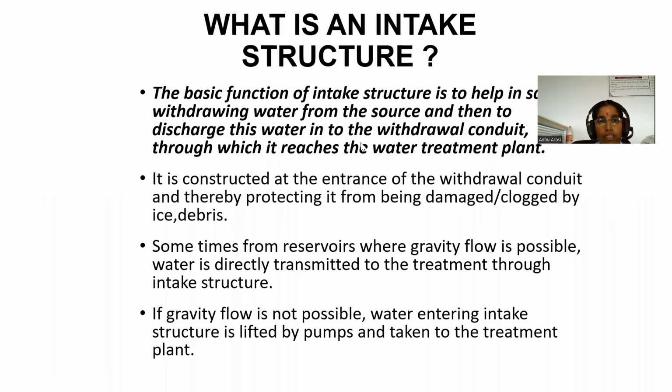Intake structures. The basic function of intake structure is to help in withdrawing water from the source and then to discharge this water into the withdrawal conduit through which it reaches the water treatment plant. It is constructed at the entrance of the withdrawal conduit, thereby protecting it from being damaged by ice and debris.